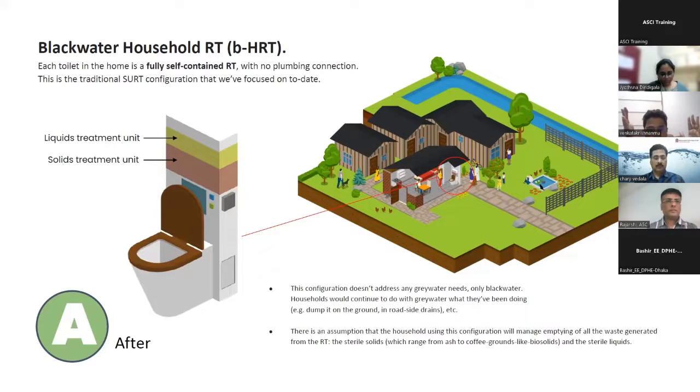This is a pictorial of an individual home. If you have a residential community with multiple stories, you will still have very little used water coming out of the system. So the sewer networks can shrink that much more. You can have shallow sewer systems, much smaller diameter pipes that carry only the gray water coming out of multiple households to a central treatment. There are a lot of ways this can work. It's not one size fits all. The technology enables you to treat everything within the facility.